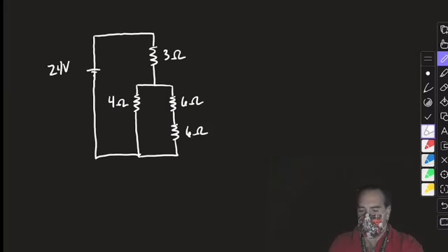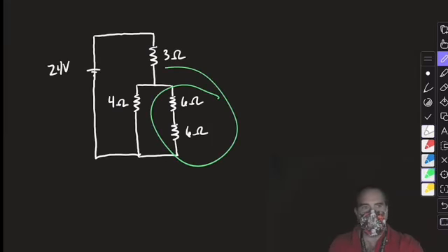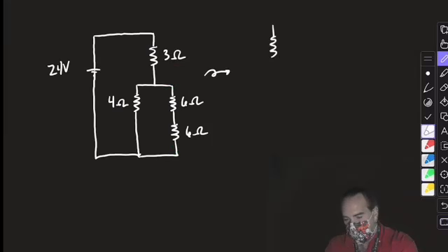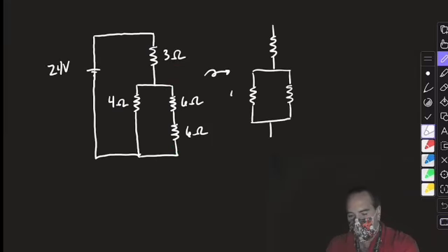So what that means is I'm going to look for examples of series or parallel. And I can only reduce a section of the circuit that is strictly series or parallel. So the first thing I'm going to do is reduce this part of the circuit. It's strictly series and allows me to make a reduction by using the rules for series. So I tend to not draw the voltage supply every time I reduce the circuit. I just draw the resistance portion. And for those who are new to this, I write in the parts that we know